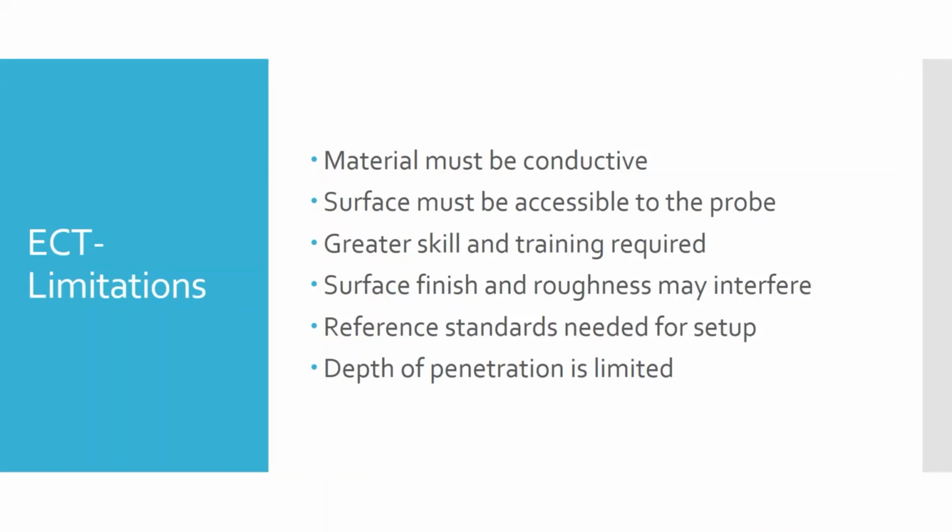This one does require a certain amount of skill and training, both to perform the method as well as to interpret the results. The surface finish can be very critical in what kind of an indication you get. And so rough surfaces are harder to inspect and can cause interference and false indications.